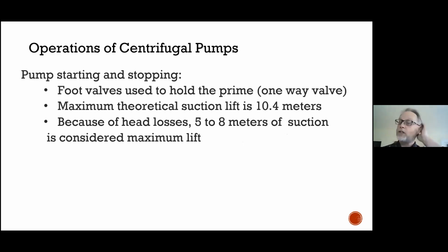Now, there will be questions about suction lift. In other words, how high can we lift water to the impeller? And this is basically just in meters or feet, but on the exam, typically it'll be in meters. So theoretical suction lift, 10.4 meters. You cannot. If you try to lift water higher than that, it won't work.